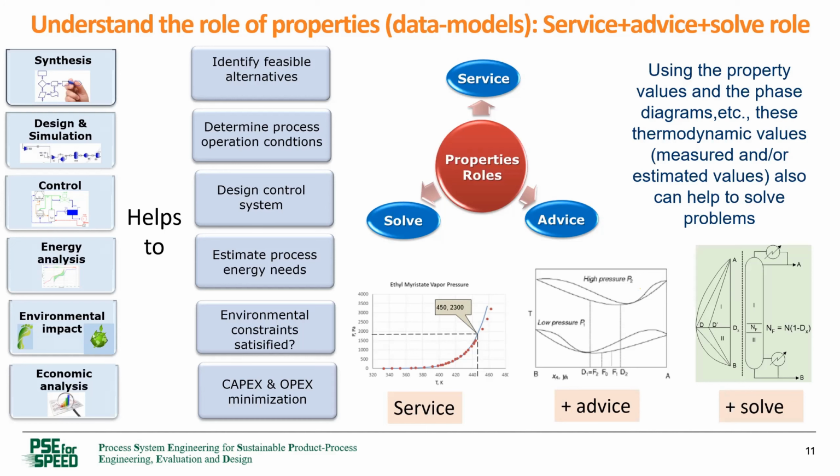Because at the maximum driving force, if we calculate all the design parameters of the distillation column, by definition, it will require the minimum energy. So what we can see is that thermodynamics not only plays the well-known service role, but it also plays advice and solve roles, and we need to use more and more of this.